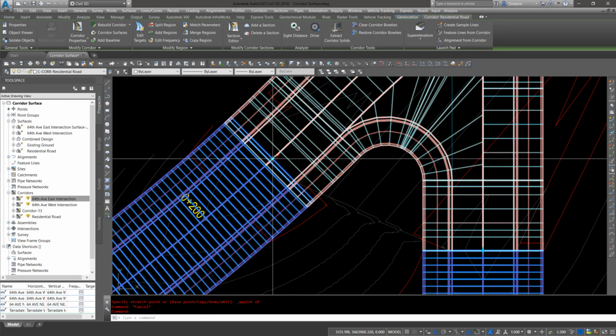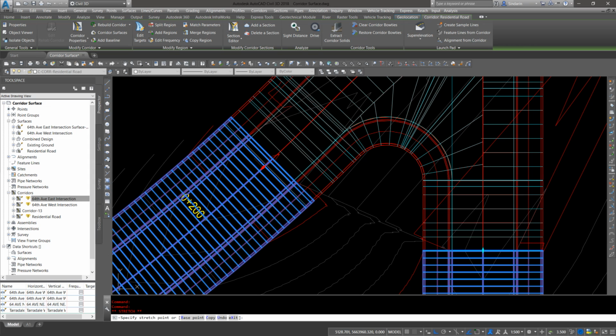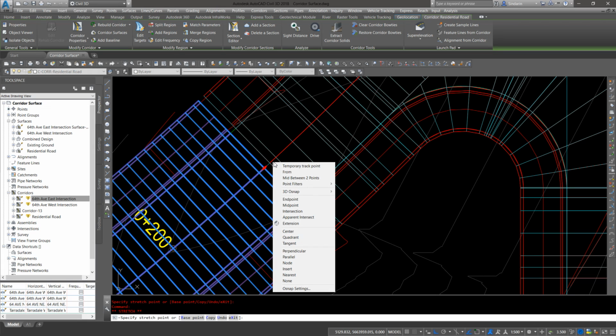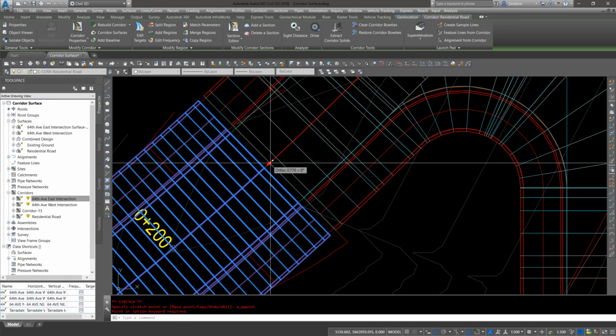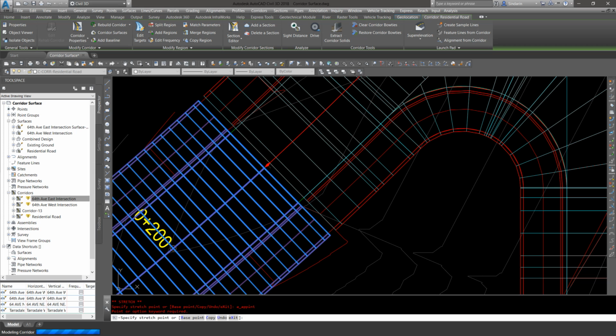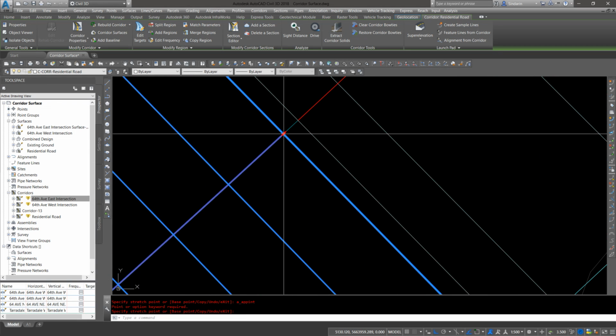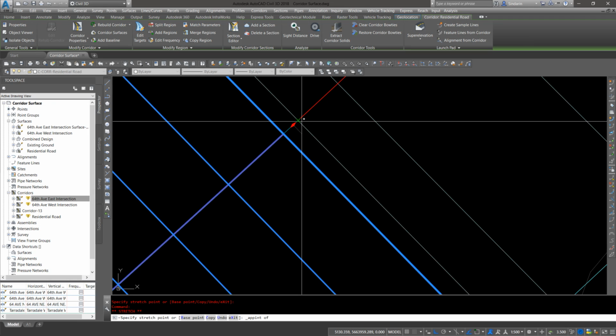And then I'm going to... We'll get there when I'm done this, but we're going to make another surface with a boundary. And then we're going to create a master surface. So we're going to take all 4 of our road pieces and we're going to put them together. And make sure you snap so you have no gaps in your data.